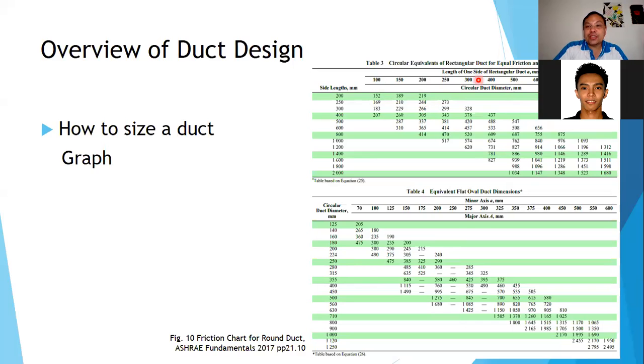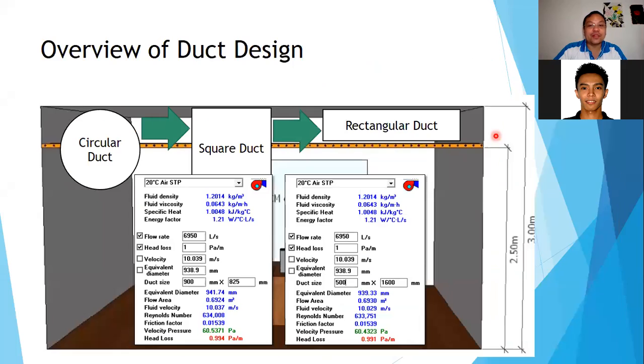So, for example, this is your circular duct. This is the flow rate. These are the recommended duct dimensions. So for example, your circular duct is 300, which means the rectangular duct is 300 by 250. Like that. When choosing, of course, there are times that the size really needs to be small on one side and longer than the other one, like really longer.